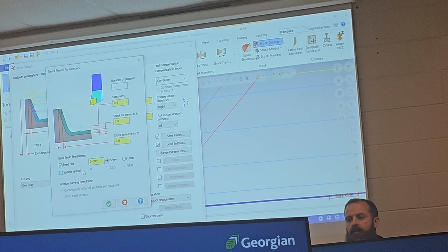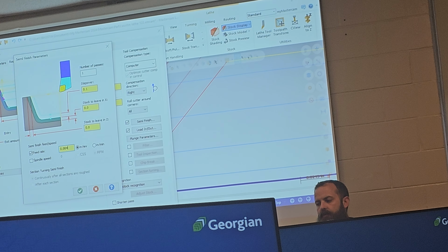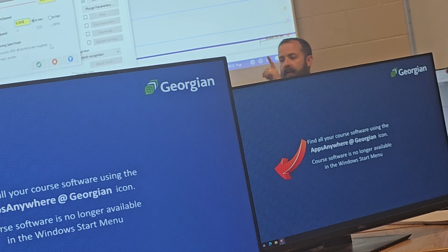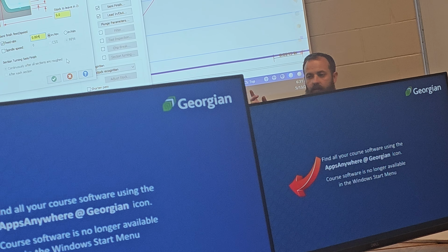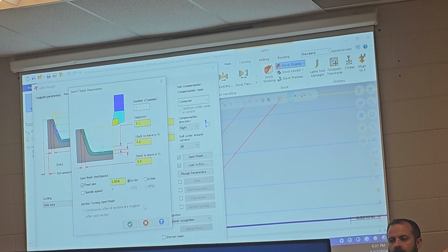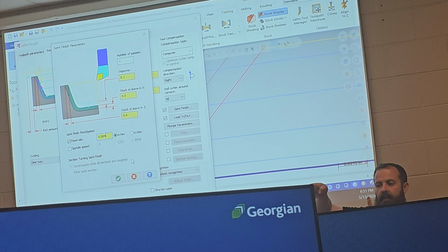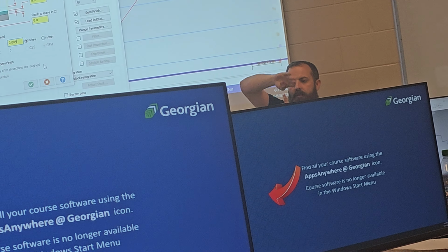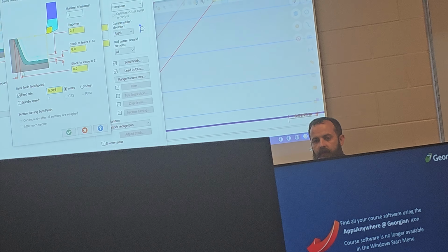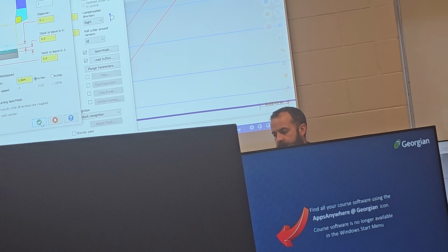As a general rule, the radius on your tool strongly impacts the surface finish related to the feed. If I have a 15 thou radius, so a very small one, and I feed it very fast, it will look like a thread. Okay, a really almost pointy insert moving too quickly across the material, and it'll effectively look like a thread. If that was a giant radius, you know, and my cusps were smaller, I could move that quicker and have a better surface finish. Because it's a small radius, we're going to go reasonably small for the finish rate.